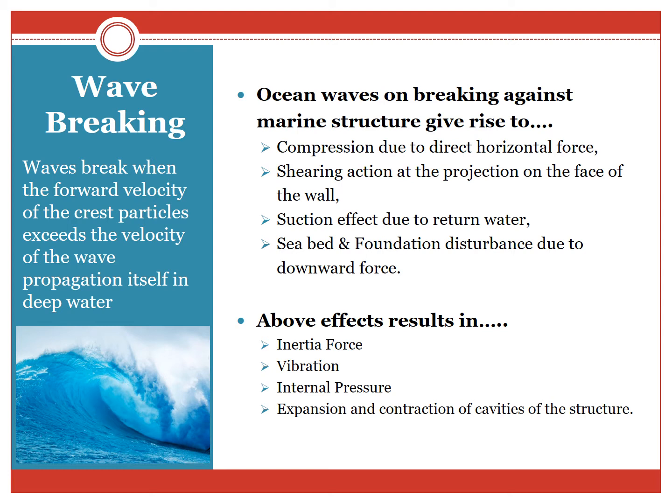First, the compression due to direct horizontal force. Second, the shearing action at the projections of the face of the wall due to deflected vertical force. Third, suction effect due to the return water after striking.